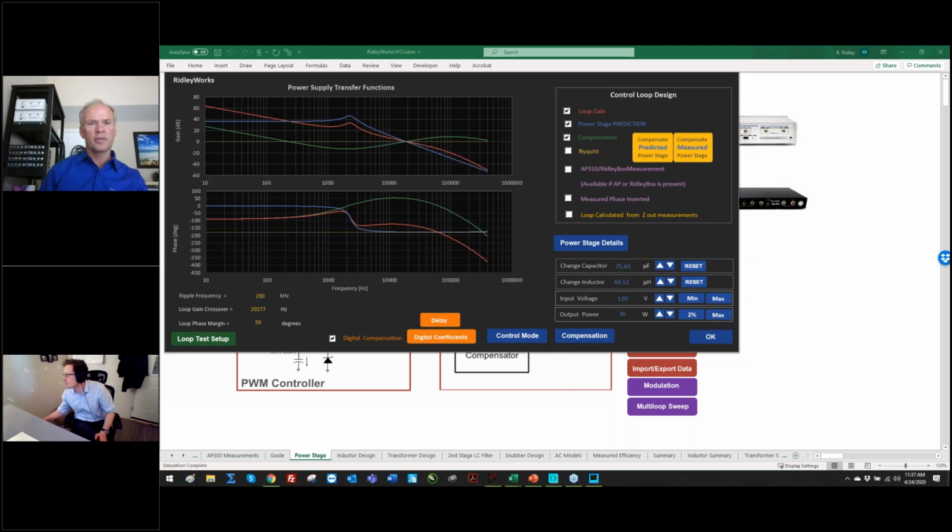Why do we still prefer using the Flyback converter? There are more efficient converter topologies. It depends how efficient you want. When we do our lab, we build a 25-watt Flyback and we get about 93% efficiency out of it. We can build that in an hour. If you want to build an LLC, you're going to be there for a few weeks doing the same job, just to get a few more percent efficiency. So it all depends. It's not just cost, it's speed of product development that keeps these topologies alive after all these years.